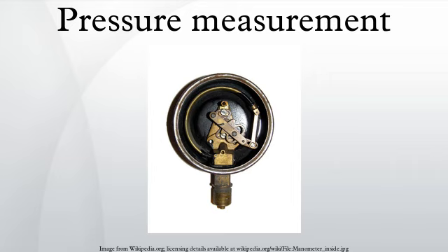Instruments: many instruments have been invented to measure pressure, with different advantages and disadvantages. Pressure range, sensitivity, dynamic response and cost all vary by several orders of magnitude from one instrument design to the next. The oldest type is the liquid column manometer invented by Evangelista Torricelli in 1643. The U-tube was invented by Christiaan Huygens in 1661.